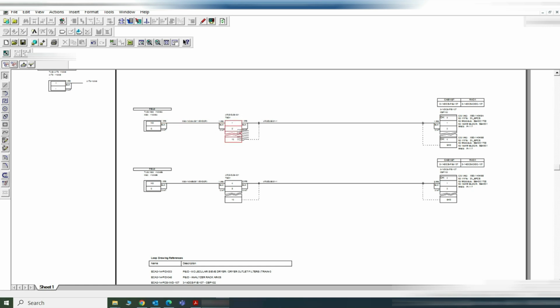From the junction box a multi-pair cable will go towards the control room. So this is the multi-pair cable and the first pair of this multi-pair. Pair 1 end 1 is connected to the junction box, and end 2 of pair 1 of this multi cable is connected to the system. So this is pair 2 of these multi cables. So there will be multiple signals connected to the same cable having different pairs.